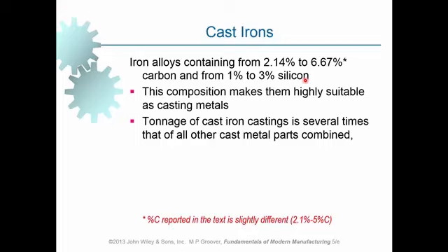We don't want that. Silicon prevents formation of cementite in the product. It dissolves it into graphite. So there will be deposits of graphite present in the cast iron if there is a sufficient amount of silicon in it. And that's what we are after.